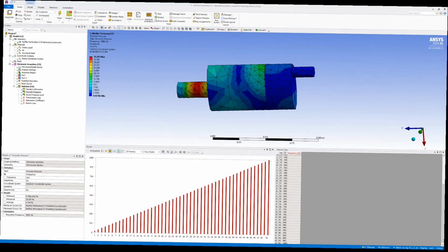And we can use this number to calculate the intensity if we also solve for the outlet velocity, which is I equals PV. So that intensity quantifies the amount of energy in the sound wave in units of watts per meter squared, which can then be converted to the logarithmic quantity decibels. And you can see throughout the frequency band range, pressure increases linearly throughout your frequency band. So let's move on to sound pressure level.